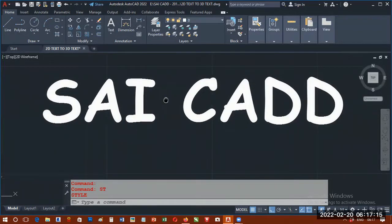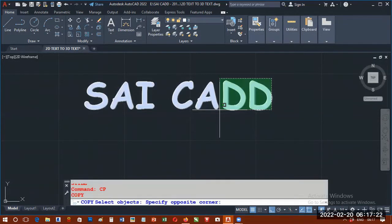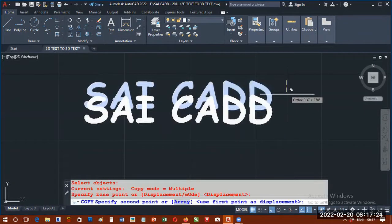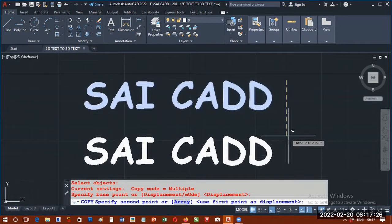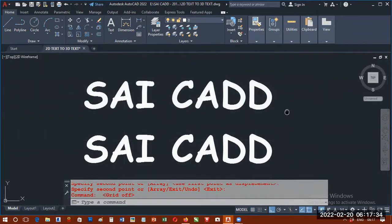Let me have one more copy of this text. CP, enter. Let me select this, click and drag down with ortho on only. Okay, so I copied one more set here. I wish to switch off the grid here. The grid is switched off, done.